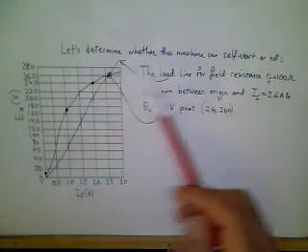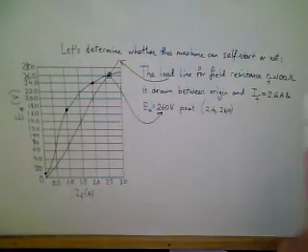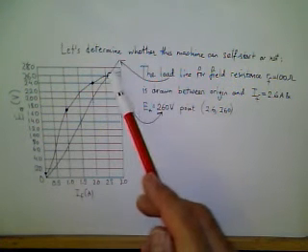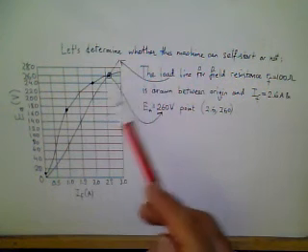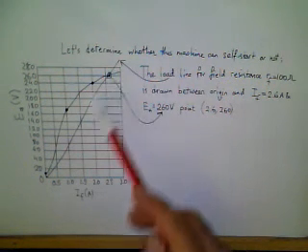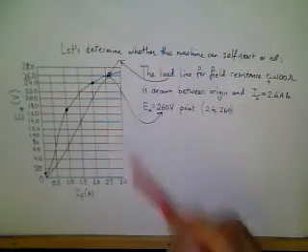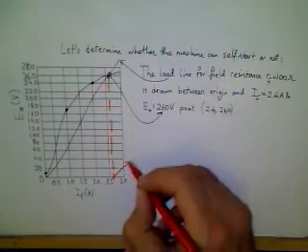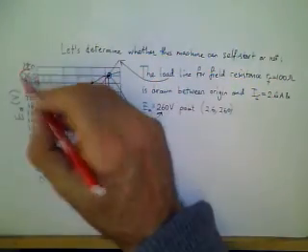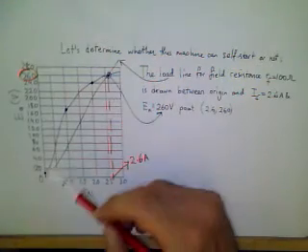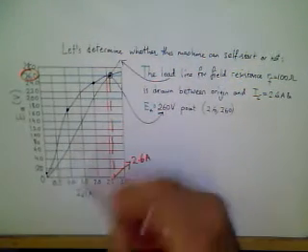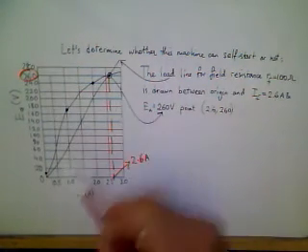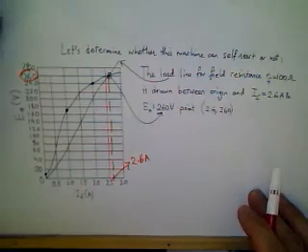First, let's determine whether this machine can self-start or not. It's because it's given in the question as well. On the same magnetization curve, we draw the load line for field resistance 100 ohms, and this 100 ohm line passes through 2.6 amperes and 260 volts. So this is the operating point. As you see, this is under the nonlinear curve, so it starts from this point and can self-start, as we will see.